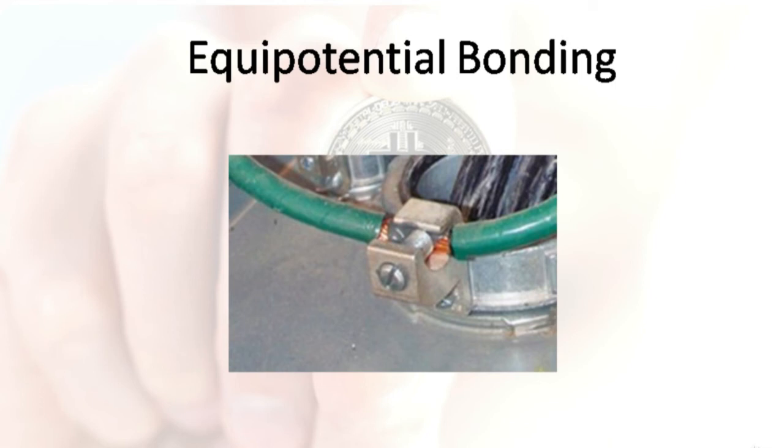Bonding should not only be just connecting the equipment, but also to service pipes, ducting, heating, and air conditioning systems. You connect all of these components through something called a bonding conductor, the size of which will depend on the anticipated fault current your facility might have.